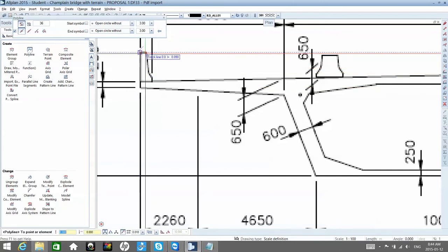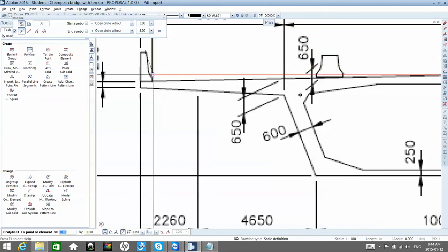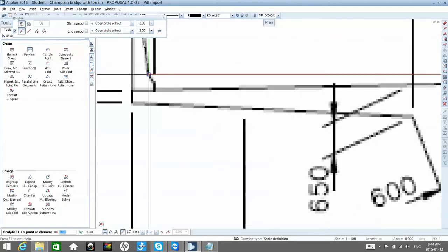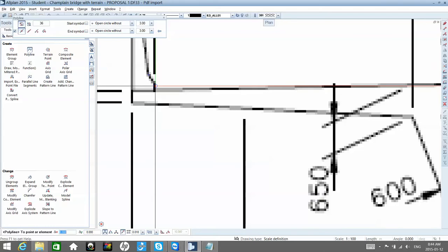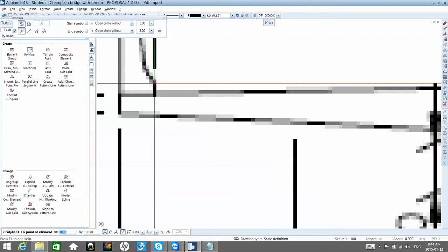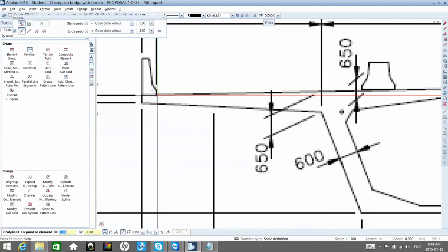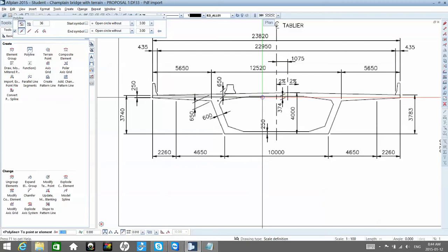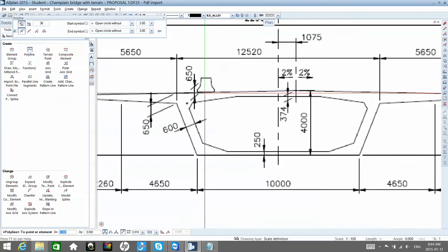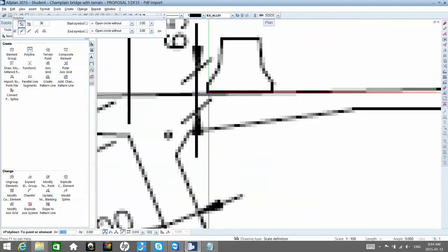So I'm going to first try to draw this over, and then we'll scale some dimensions to be close to the real cross sections. But it's better to do the dimensions on the vectorized element than on this pixelated one, as this type of element, the BMP, is pixel based, so we can't snap to pixels.